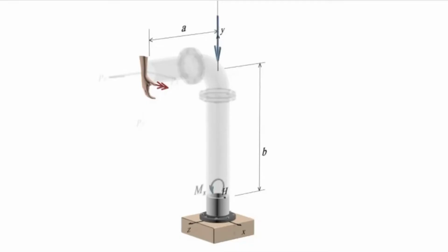The second move would be moving this force downward. When I move this force downward, once this force arrives at that point, that would be an axial force because this force is perpendicular to the cut section area. On the other side, this move is not producing any extra moment because the force has traveled along its axial direction, right? This force is producing two components.